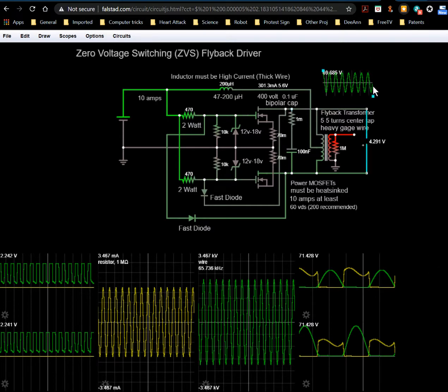You can see as this voltage approaches 0, this is getting ready to change. This transistor here, you can see it highlight, is coming out of conduction because it's yellow, because it was conducting. The current that was flowing through it, the voltage was 0-ish that whole time, but the current was high. Here the voltage was high, but the current is 0-ish. So this is about to turn on. This is in the process of turning off, and this is in the process of turning on. You can see the current start to increase here.